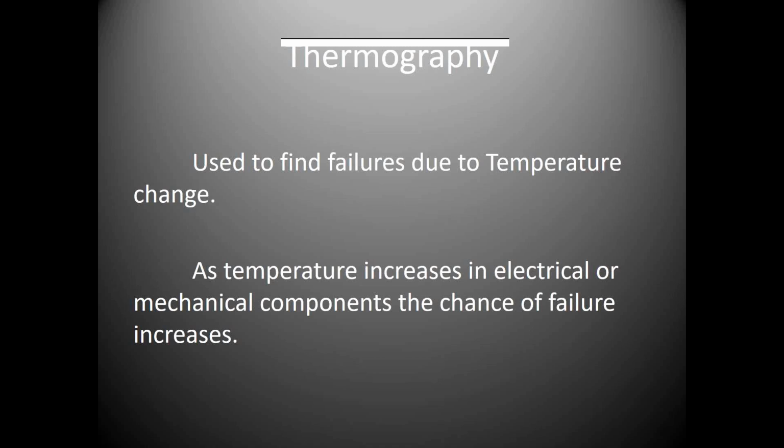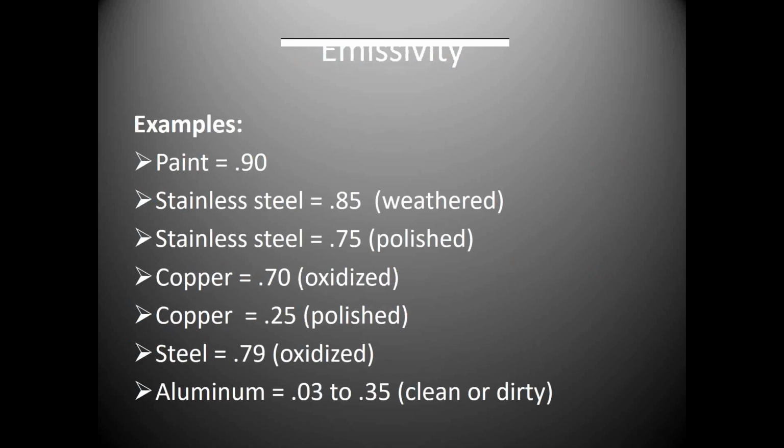Now we get into another technology here, thermography. It's used to find failures due to temperature change. As temperatures increase in electrical and mechanical components, the chance of failure of that component actually increases. So what are some techniques we can use?